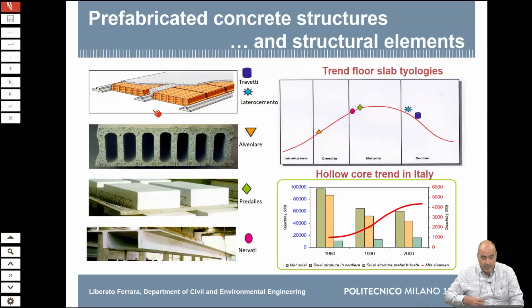And well, an overview: as I said, it all started in Italy from the prefabrication of these beam elements for slabs. It was quite common to have this beam and block system, completed by a cast-in-place pouring, so that you have a T-beam formed by this precast element, the poured concrete, and the top slab. And these clay blocks had a twofold purpose. First of all, to reduce the weight. But they also have a minimum of sound and thermal insulation capacity. So, for example, you do not hear your neighbor upstairs or downstairs when he shouts and so on.